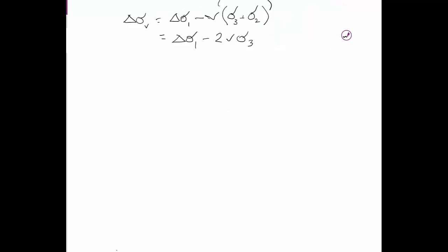Okay, before I go any further, I do realise I stuffed up the numerator and denominator in that previous section, and while I'm no Spielberg, it takes a bit to do these things and you're thinking of 4 things at once, so I don't want to get 100 emails about that. Okay, so we know that the increase in vertical stress is the change in the sigma 1 minus 2 times Poisson's ratio times sigma 3.